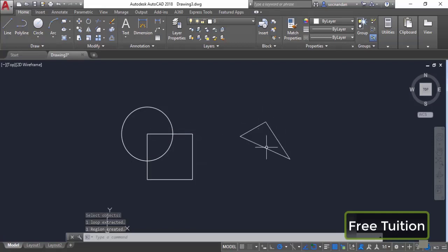Now I'll convert this object into a region. In this case, you can see that we can select it separately. Let's now go to region tool and select all of these objects and press enter. Now when I move my cursor, you can see that we have a region here as seen on the tooltip, and the complete geometry will be selected. So in all of these three cases, we had completely closed geometry. That's why I was able to convert them into region, and that's one of the conditions which needs to be fulfilled for converting an object into a region.